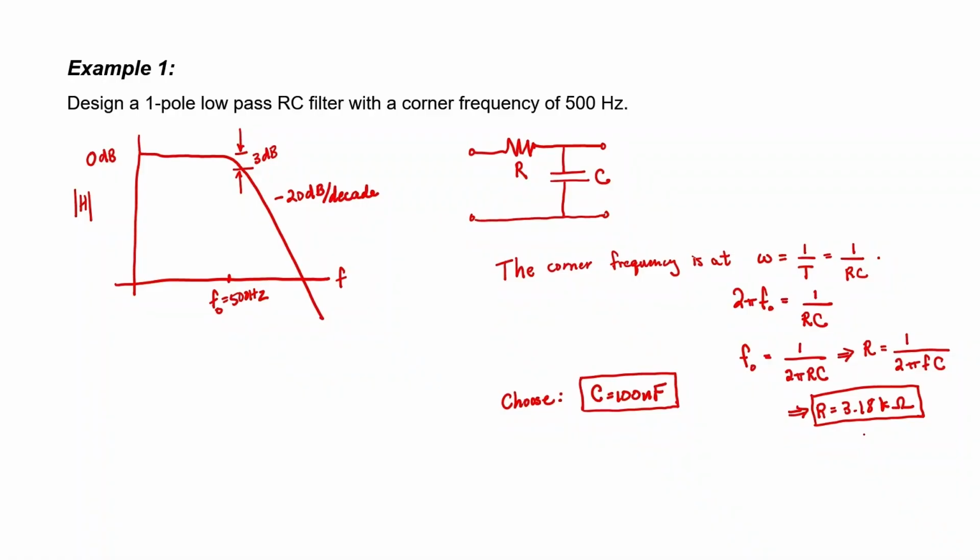We don't want a resistor that's way down deep into the ohm range, like 10 ohms or 20 ohms, and we don't want resistors to come out super high, like 10 mega ohms or something like that. Tens of kilo ohms, that's good range, so we'll stick with this choice. Keep in mind though, that if we use this filter in a circuit and the load is somewhere in the neighborhood of R, then we might start to have a problem. If my load, for example, were hypothetically a mega ohm though, this filter would work perfectly well and the corner frequency wouldn't be altered.